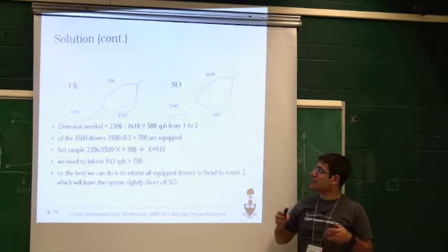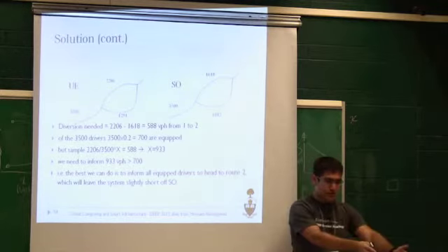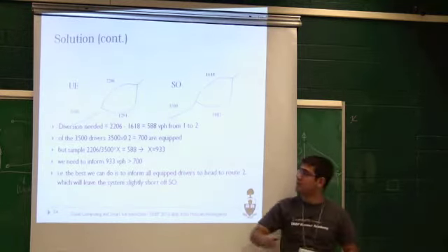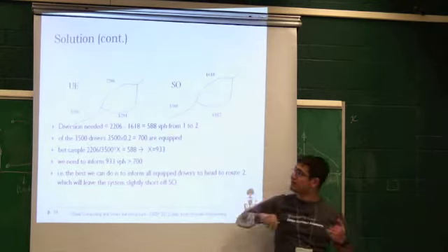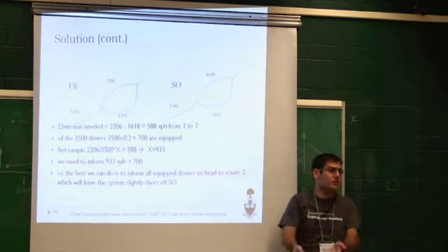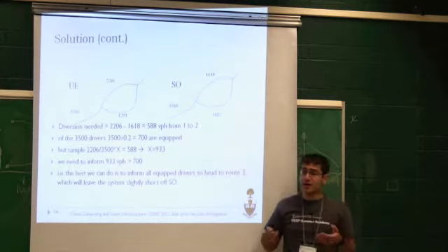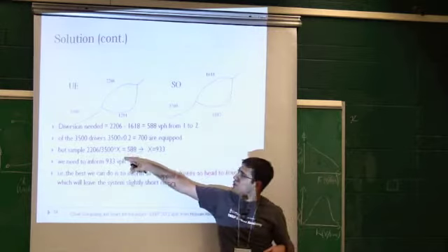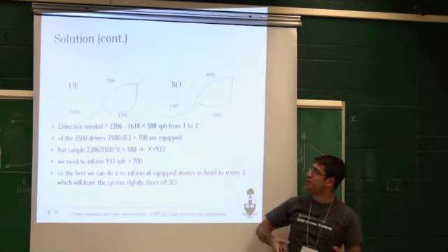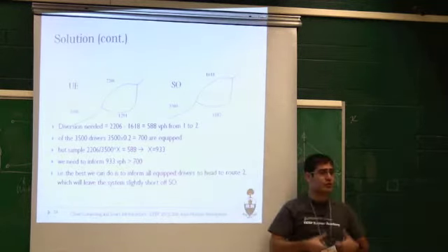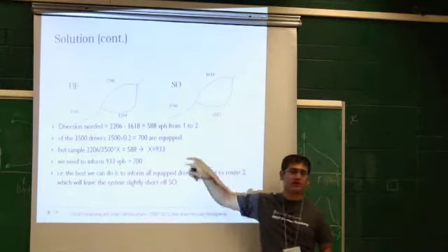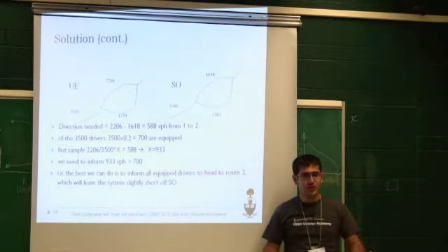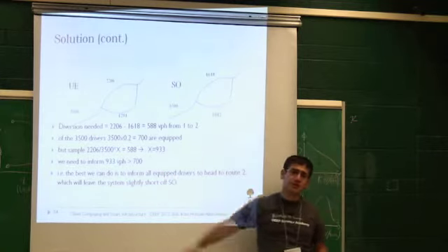That's why I need to take into account that I can communicate with 20%, but out of the remaining 80%, the exact number of people who are going to go to route 2 is less than 1294, because it's 80% of 1294. That's the remaining. That's why I'm using this formula to make sure which percentage of people that were going to user equilibrium I have to actually shift. And the total value that I end up with is 933, which I can't reach, but I will settle with something close to it.